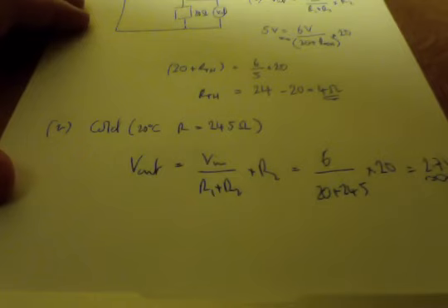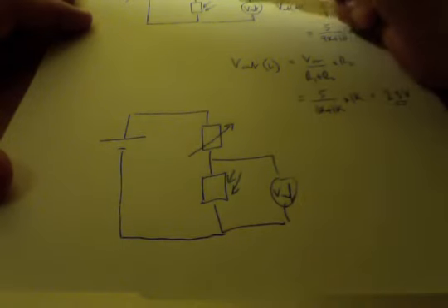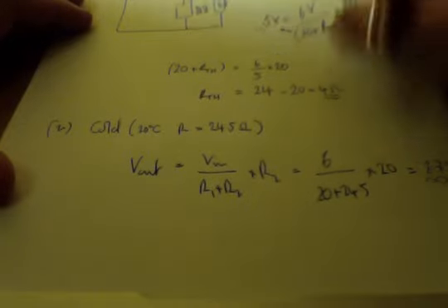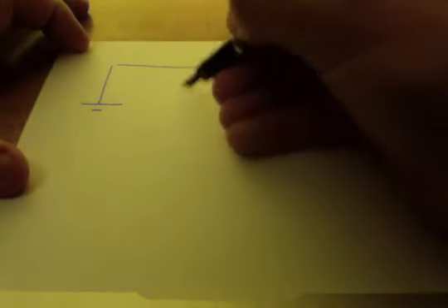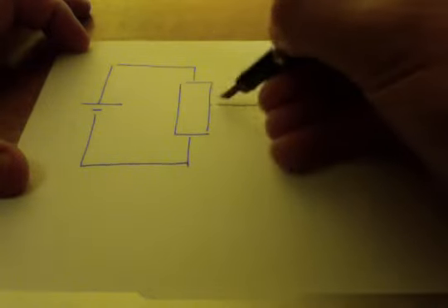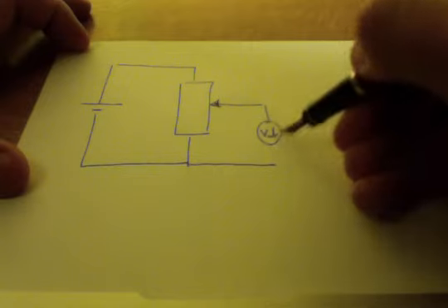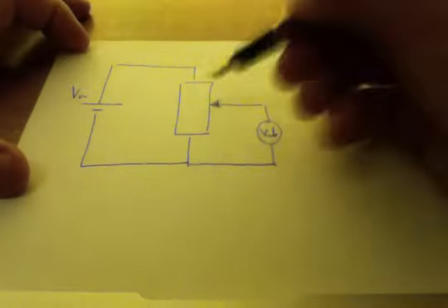Now, I just want to draw you back to this idea that you could only get this range between 4.5 and 2.5 from this setup. You'll only ever get a range. If you want to get a full range, then you need to turn to what's known as a potentiometer, and I'll show you why that is useful. Now, with a potentiometer, rather than having 2 individual resistances, you take a point between these two.